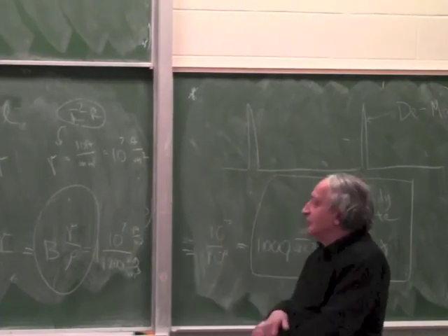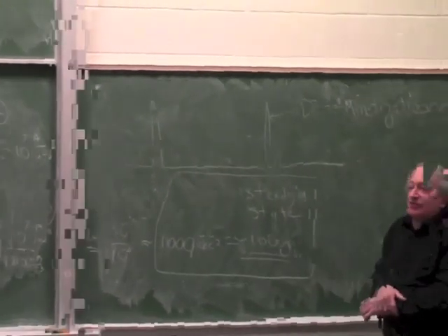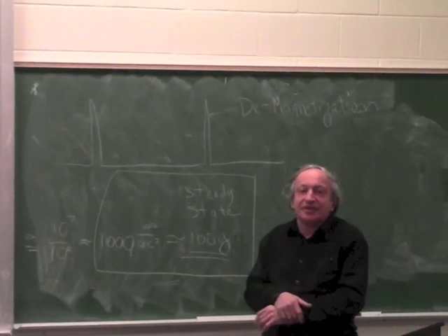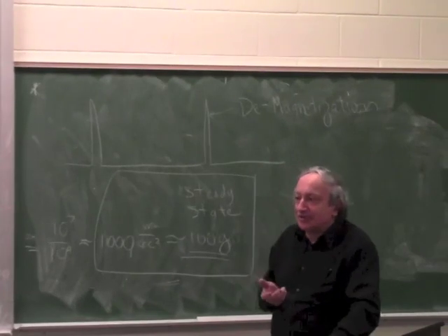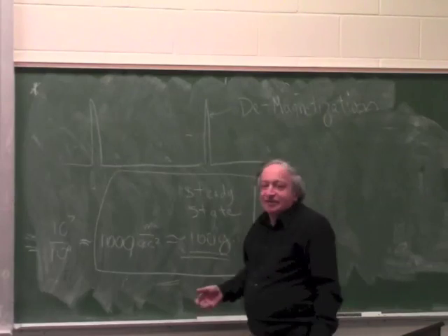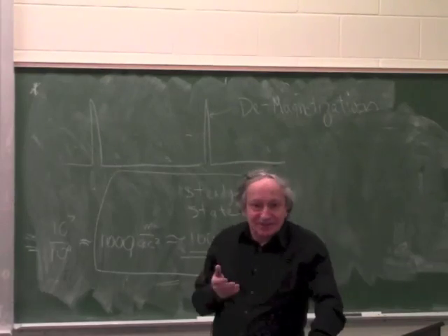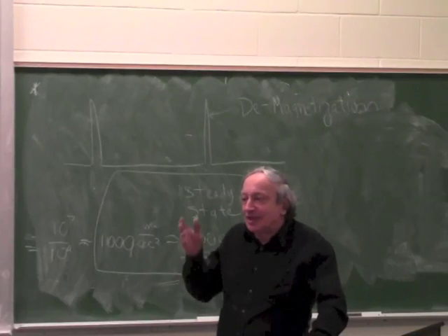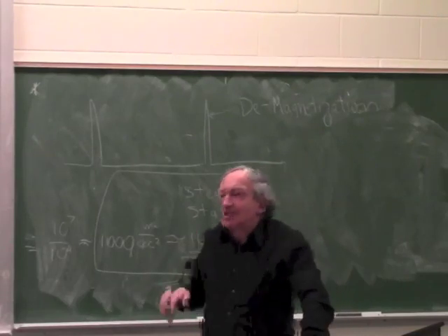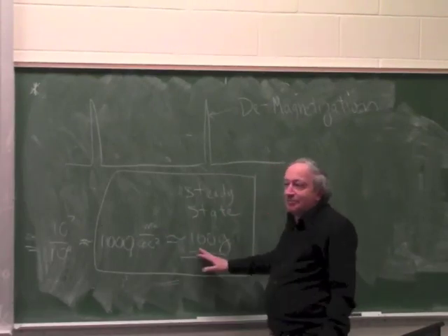So the bottom line is that if you have to design a servo, and the servo has an actuator which has to do much better than 100 G, you're looking for trouble in a steady state. If it has to do more than 100 G in pulse, it's no problem. In pulse mode, you can easily go 10 times that number.